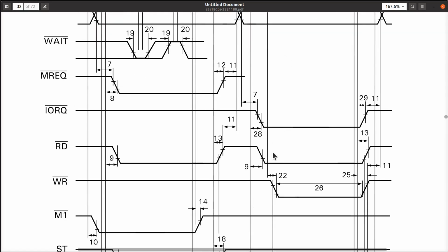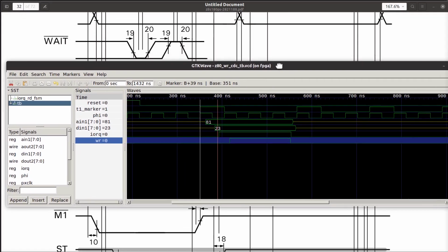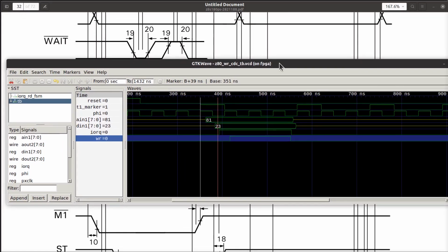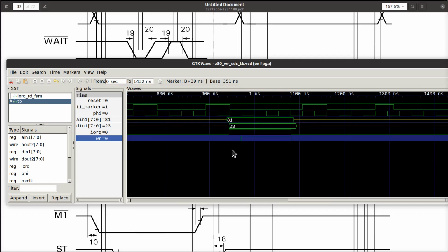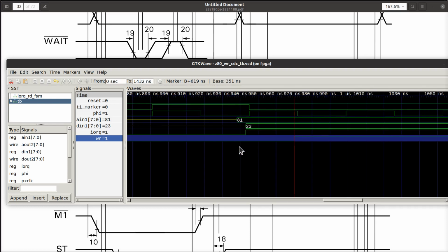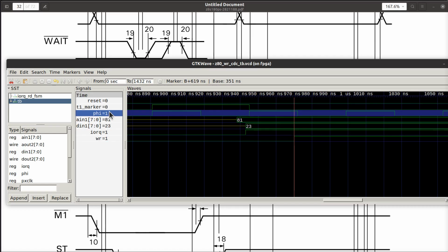Just for a mental picture in my head. My timing diagrams up here are actually going to be accurate and correct, even in the worst case scenario, which I think is over here, in that these things will happen if we zoom in a little bit here. For example, this is your 25 nano after the rising edge of T2, which is ever so slightly before the falling edge, because this thing here, as you saw before, is not running at 20. It's slightly slower, which means this is a little bit longer, so mine will sneak up a little bit early, okay?